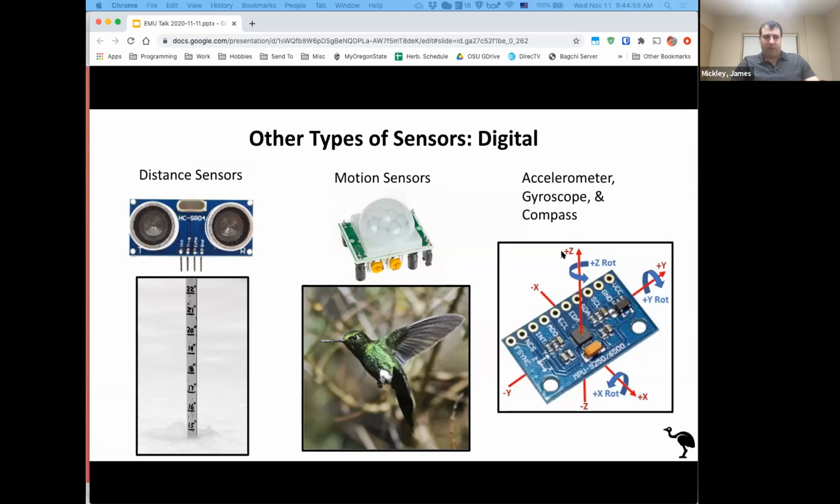And another researcher that we cite is using Arduino-based systems to measure water flow in caves in Mexico. They have an accelerometer inside a tube of PVC that's sealed, and it's set up like a pendulum. As the water comes into the cave, the pendulum swings, and they can measure that amount of swing and turn it into data.